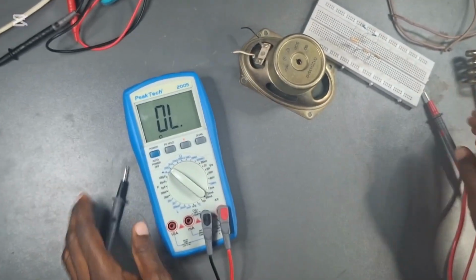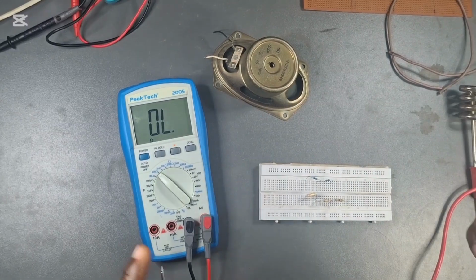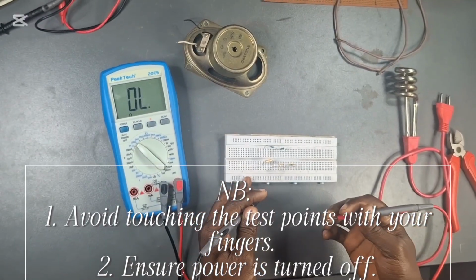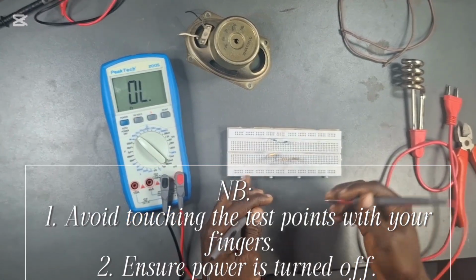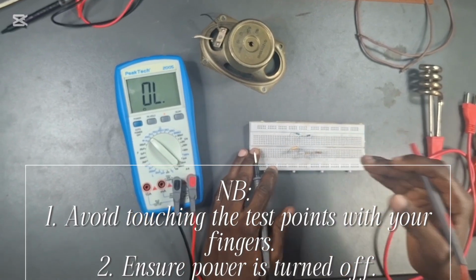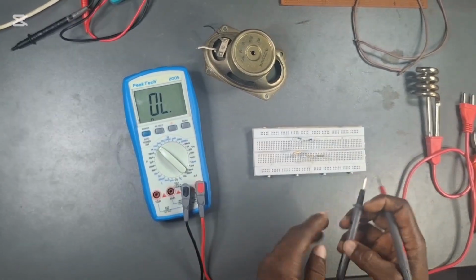One thing we need to take note of is that any time you are measuring resistance, you need to ensure that your fingers do not touch the test leads, as this will alter the measurement that you are taking. Another thing you also have to avoid is to ensure that there is no power on the circuit when measuring resistance. Okay, so that will be all for resistance.